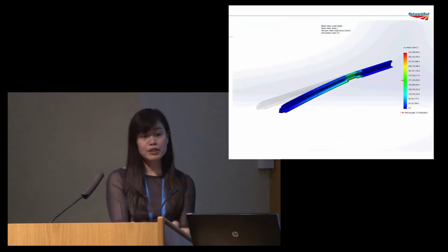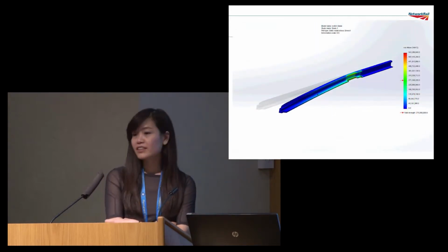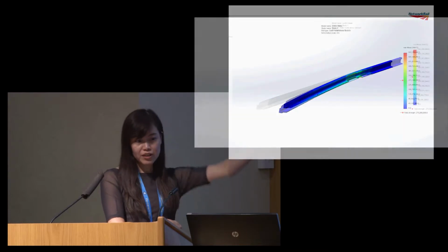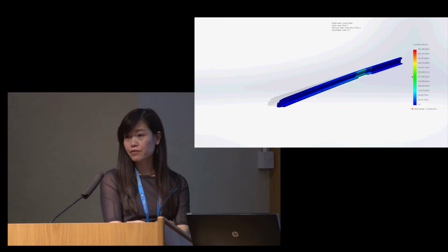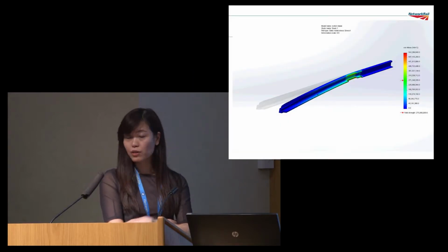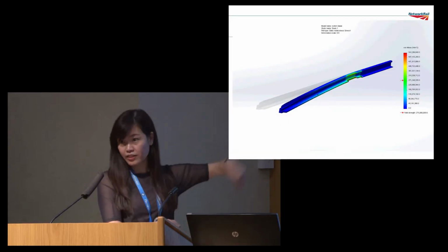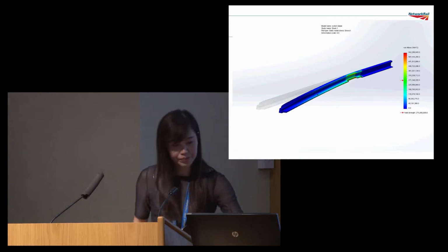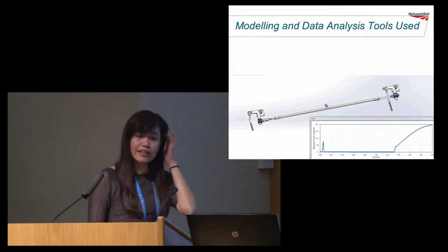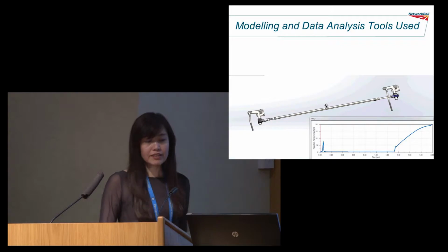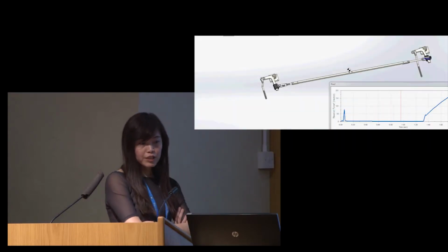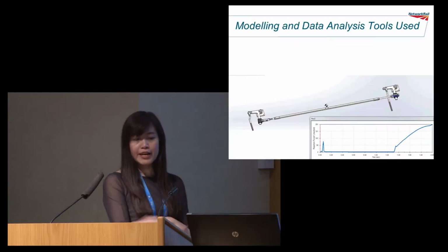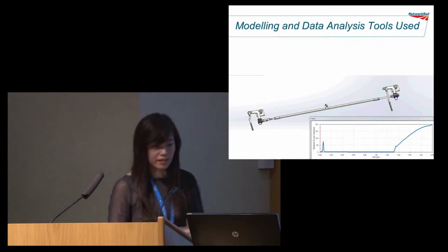And this is a switch flexure model that I'm looking at. I can put a force anywhere along the switch blade and see what the reaction force is at the back of the switch, and also what the stress level is at the cutout at the foot. I'm also looking at the supplementary backdrive. This is a model of the supplementary backdrive for a CVS switch. The graph there shows the reaction force on one of the crank bases. Okay.